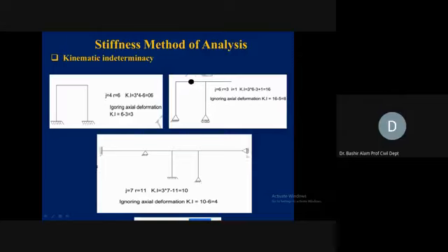And then 1 from this roller support in this direction, so 10 plus 1 is equal to 11. So we have R equal to 11, and we can use this equation. This is becoming 10 degrees. Then we need to take away, if we ignore the axial effect, the number of members. So this reduces to, you can check it, 4 degrees.